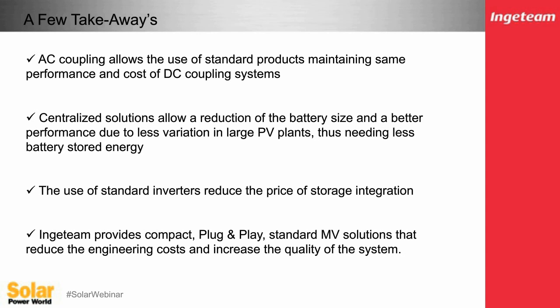The standard inverters have advantages for O&M, for spare parts, and for training of the technicians to maintain the plants. And finally, the compact medium voltage power station solution is an optimization of each individual PV or each individual battery plant for a total system balance of system optimization.